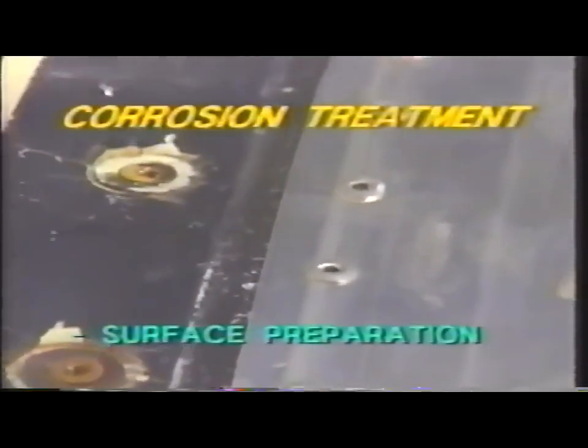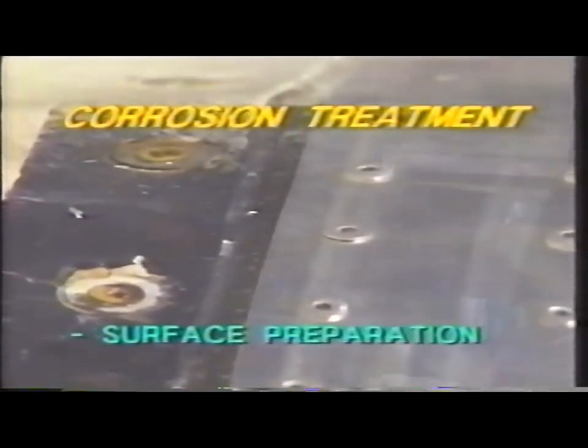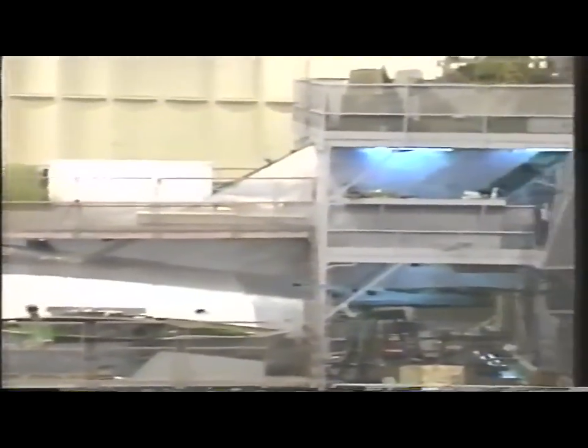Once you have made the determination that the damage is within the manufacturer's rework limits, you must treat the surface to prepare for repainting. Each metal used in aircraft construction requires a different type of treatment prior to refinishing. Here we will look at aluminum, but full details for each metal are in your AC 43-4A.